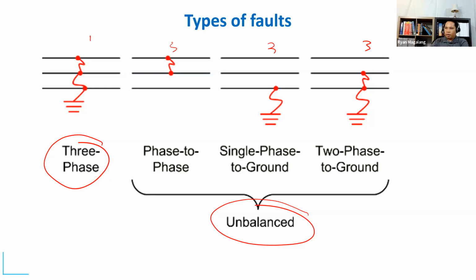And the tool, I believe you know which is that tool, is the symmetrical component method. That is the one we use as a calculation technique to calculate for unbalanced faults, which involve line to line and ground faults.